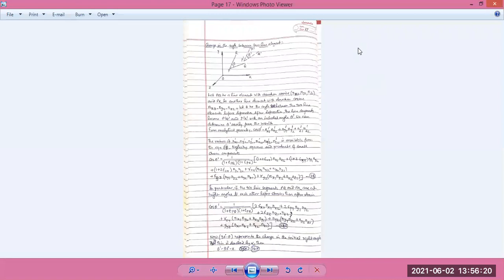Now, we have gone through the change in the volume. What is the change in volume in terms of deformation itself? Well, the original volume was there. This was a parallelepiped. After the application of the load, that parallelepiped takes a new form, and we go through what is the change in the volume itself. Now let us go through what is the change in angle between two line elements. What is the change in angle?